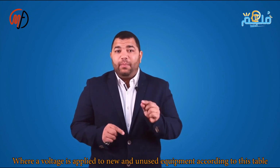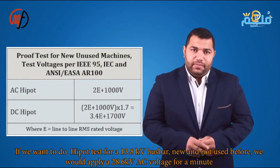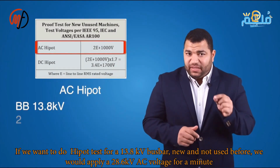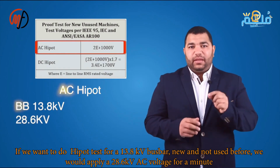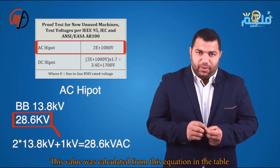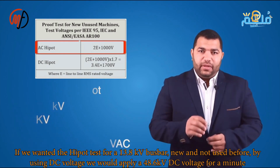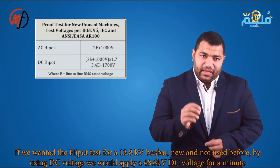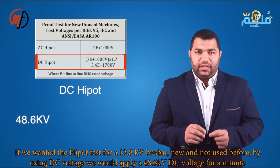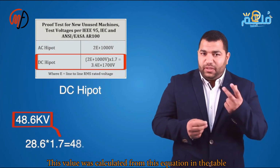For used equipment, apply 20.7 kV AC to each phase for 1 minute, which is 1.5 times 13.8 kV. For DC, apply 31.59 kV, 65% of the new equipment voltage. This value comes from the equation stating AC voltage is multiplied by 1.7.